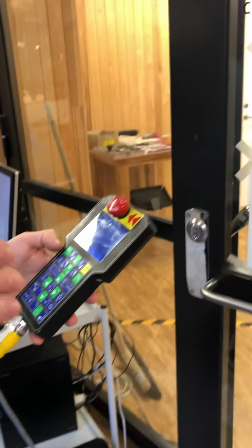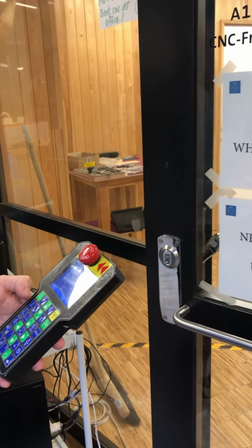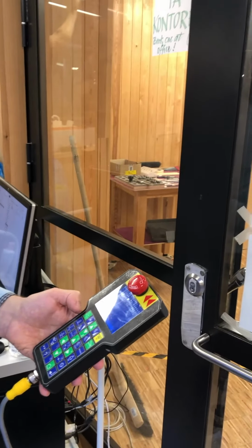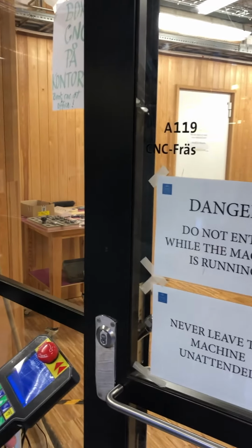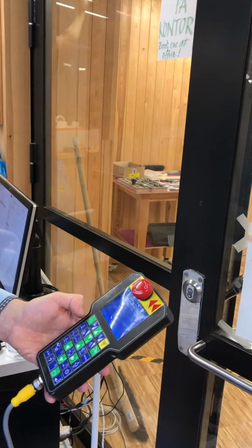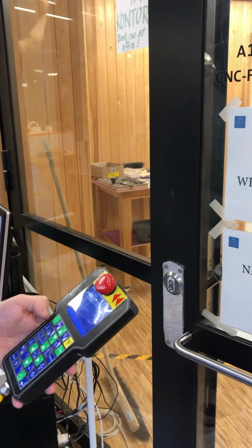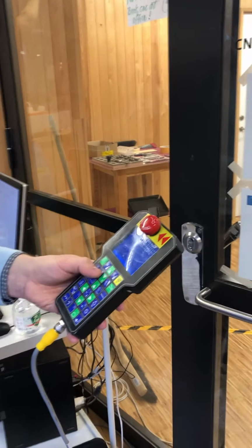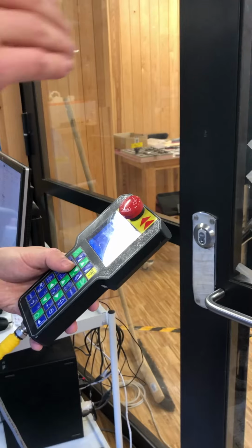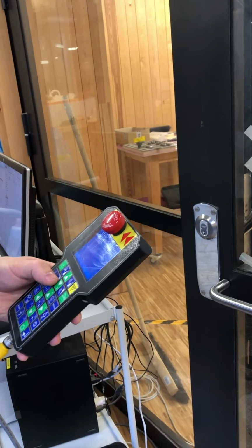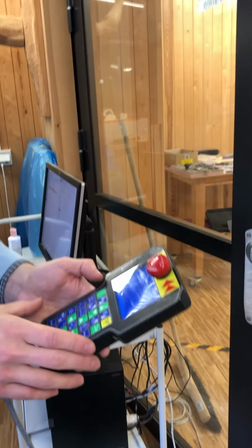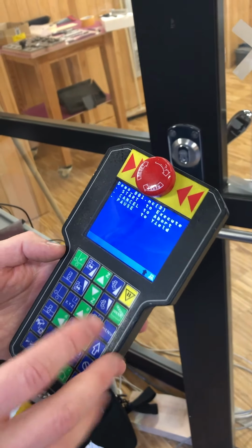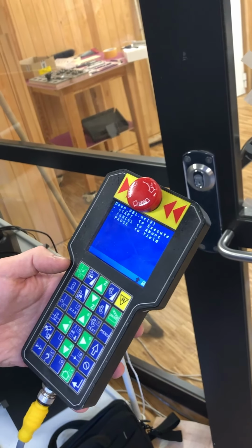Exactly. Yeah. So if you set a far too low feed rate, then you will need to go back to Fusion and redo it, or recompute, set a new feed rate and recompute. But if you are intentional and aware that you are perhaps starting at a feed rate that you have not tested out yet, then as soon as you press execute, you can decrease the feed rate, and then you can push it up sequentially and feel the material, so that it doesn't start at 100%, at way too high. Yes, but with the RPM, with the spindle speed, you can always increase it or decrease it how you want.